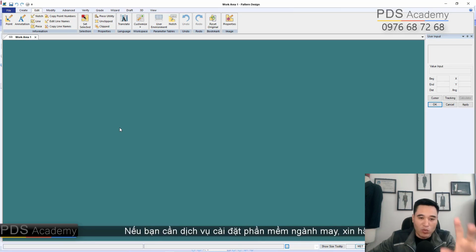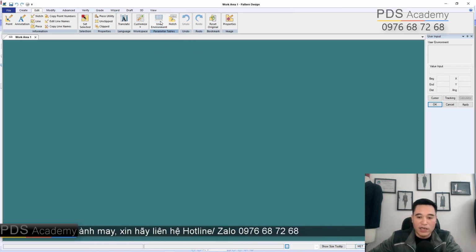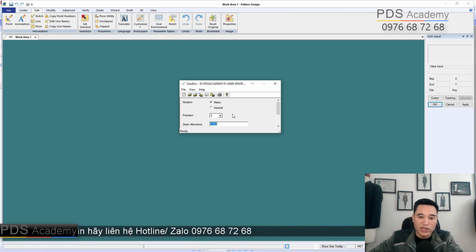If you want to switch to inches, navigate over to the edit section. Go to the user environment section. Simply click on that option to open it, and then go to the specific section where you can modify your preferred measurement system settings. If it's metric, it's in centimeters, otherwise imperial is in inches. So it depends on these two units of measurement. After you select the correct unit of measurement, click this Save button. This unit of measurement will be saved, and when designing, it will use the correct unit of measurement.